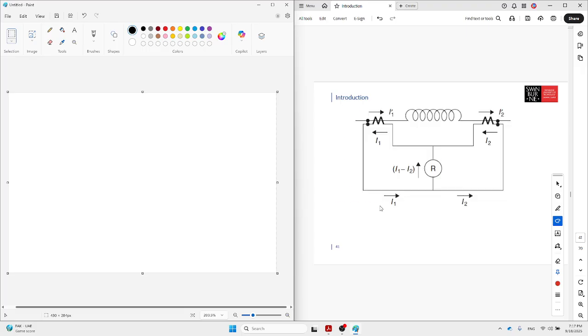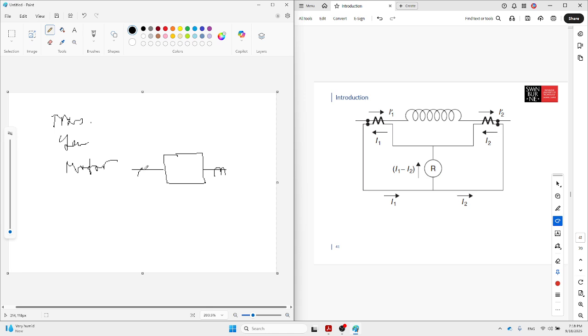Next relay is differential relay. What is differential relay? It is used for very expensive parts of the power system, such as transformer, generator, and motors. We use differential relay in the way that we have something, whether it is a transformer, generator, or motor, and then we check that the total current going in and coming out is exactly the same. Operation of this one is exactly the same as RCD.